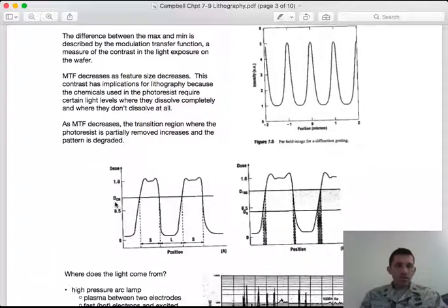And so you can see here this D sub CR, this would be like sort of the critical dose of light that is required, right? So it means that once I reach that critical dose, ideally, it would change, and so the pattern that I would leave behind would be, right, I would have solid photoresist in this region where I did reach this critical dose, and then I would lose everything else in between where I didn't reach that, right?